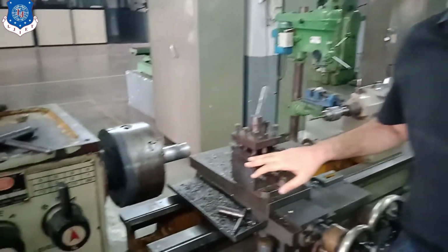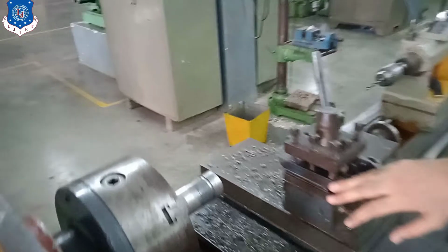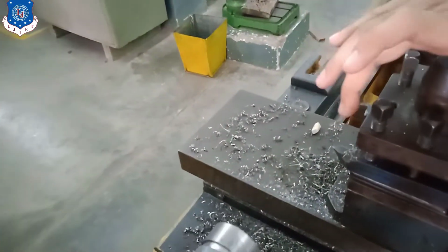For that particular threading operation, we require a certain type of automation of the lathe. That means some portion manual, some automatic. Whenever the operation is carried out on the lathe, some of the portion will go for automation. Now how are we going to do this? First of all, the tool which we require is known as a V tool, which we have placed over here. So the V tool is placed in the carriage.